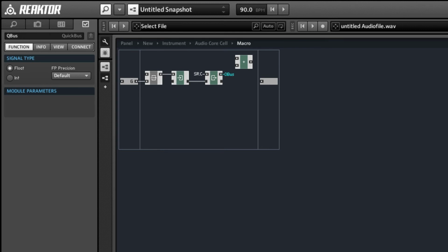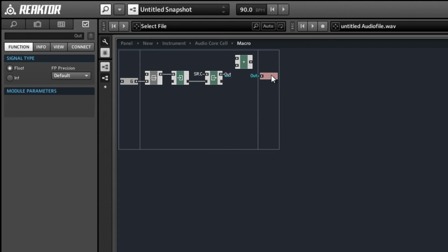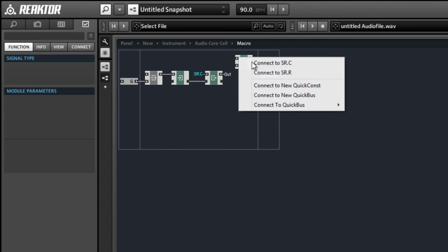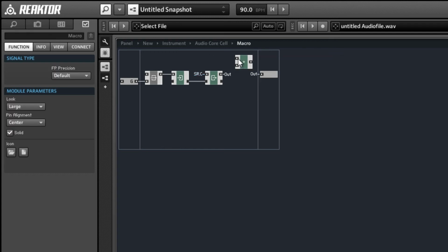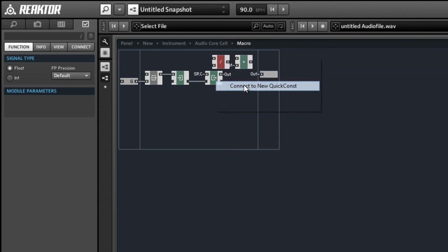So at every sample clock, we're going to read the value that we have stored, and I'm going to send it directly out. And this way, when we set the counter to be 0, that's going to happen in between audio ticks. And when the next sample clock arrives, we'll send the value of 0 to the output of our macro. And then we'll add a small number to that, which is going to be 1 over the sample rate.